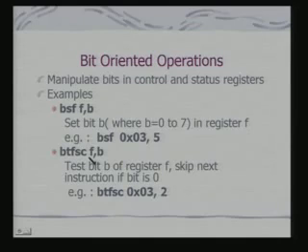This is, again, an example of a branching instruction. And this branching instruction is on the basis of testing a particular bit of a register F. So what we say is that we skip the next instruction if the bit B is 0 in the target register. So this is the target register and we are actually checking for the bit 2. This is again a conditional branch instruction. So conditional branch instruction means you will be skipping the next instruction only.